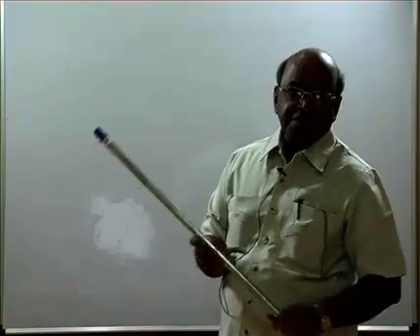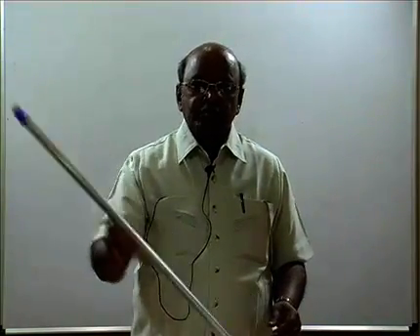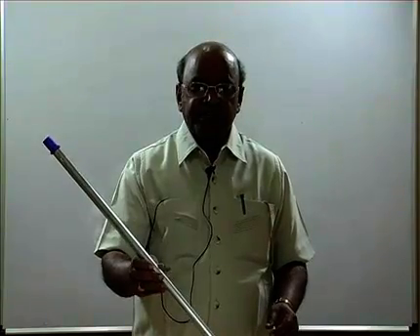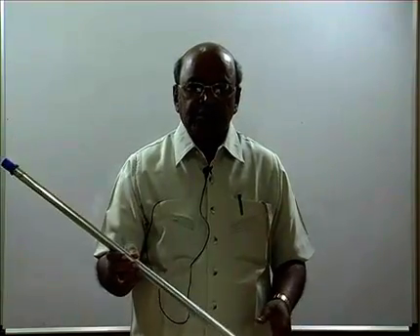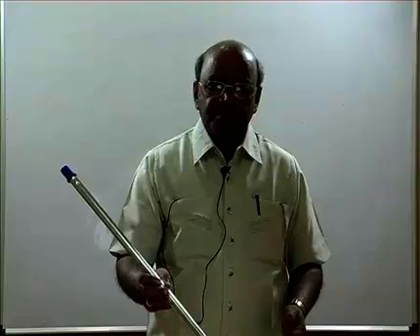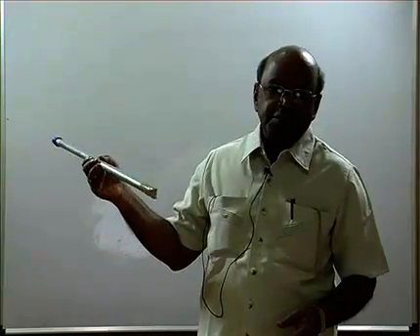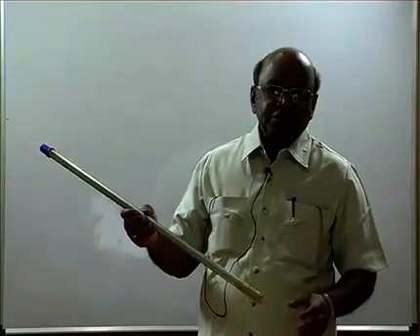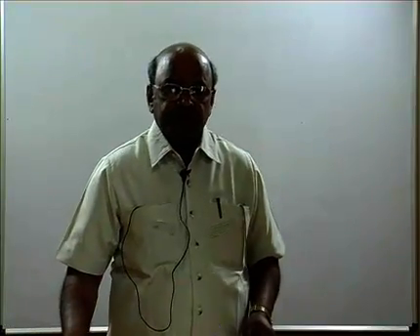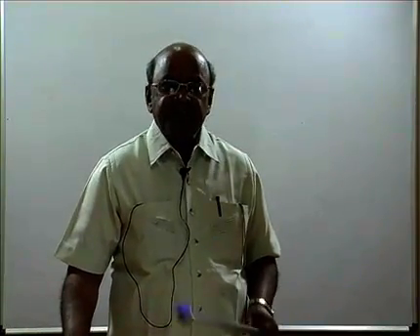So a trace is nothing but the point of intersection of the straight line with the reference planes. So maximum you will have two traces. If it meets the horizontal plane, you get the horizontal trace. If it meets the vertical plane, you get a vertical trace. This is how we will start with the 4 different cases. Before that, how to name these traces.